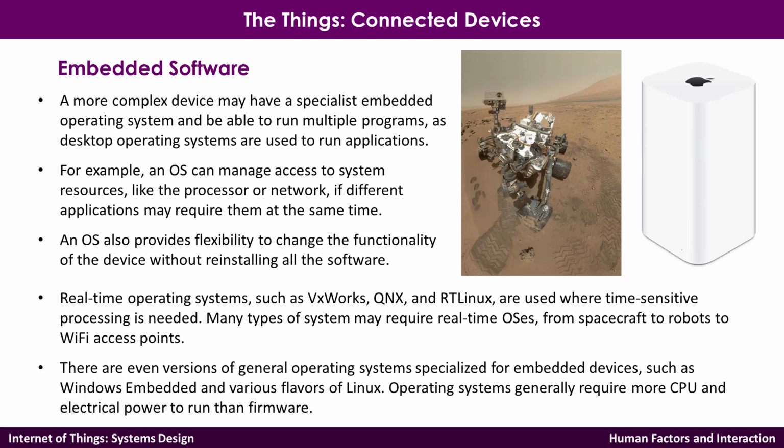So that is an advantage, but it is not popular with IoT developers at the moment, because we previously discussed that embedded systems are supposed to be very small. You don't want to give away your processing or computational resources to an operating system. Rather, you would like to use them for your own application. When you install a general purpose operating system on your computer, whether it is Windows, Linux, or Mac OS, it consumes a large amount of resources, storage, memory, and CPU, even if you don't run any application on top of it.